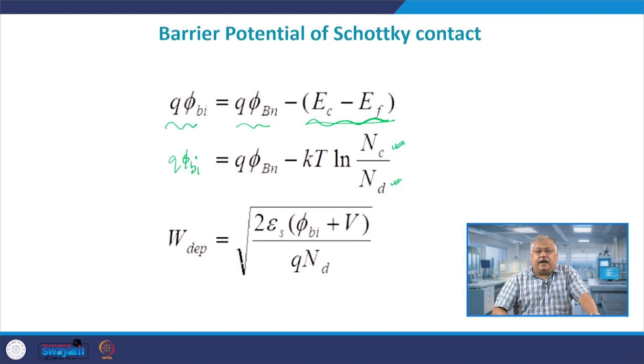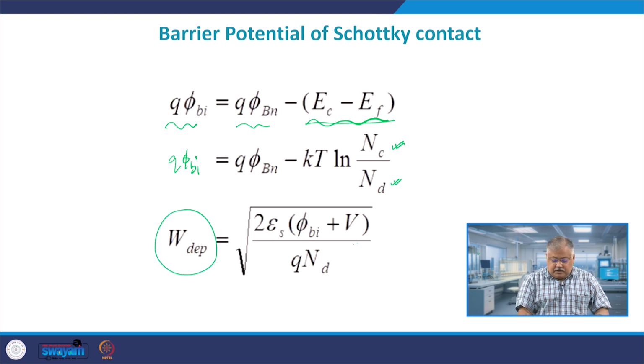So, once you attach an N type semiconductor with metal, you tend to have a depletion region available, because of the surface charge. Some electrons will leave the metal and go towards the semiconductor, or from the semiconductor they will try to go towards the metal. As they go towards the metal, there will be donor atoms available, which will give rise to a depletion thickness.